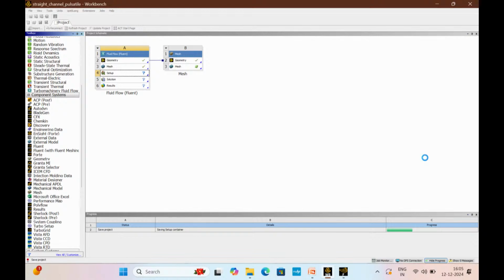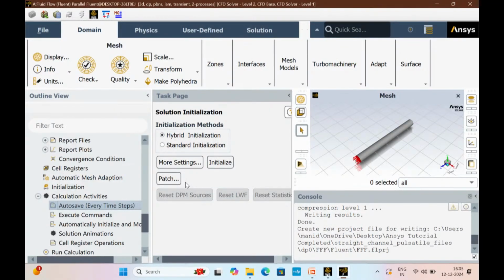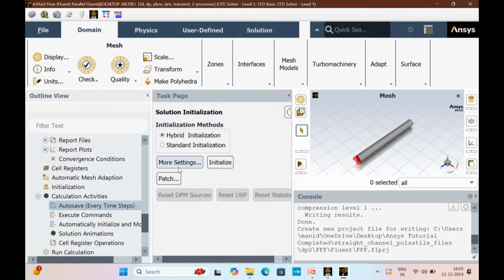You have to be very careful when you choose this, because once your simulation is done, if you need some intermediate data, you have to run it again. So, based on the profile, check which data you need for the explanation. Maybe a couple of peaks, a couple of bottoms, and then choose those times. It is actually better to save every time step, but that needs huge space, and your simulation will also be very slow because it will take time to save. So just do some calculation before you do that.